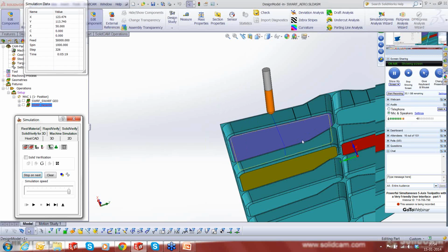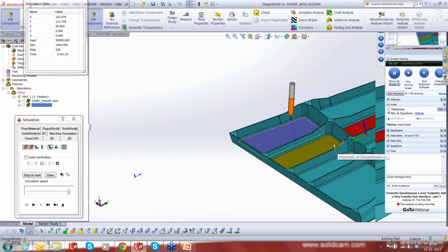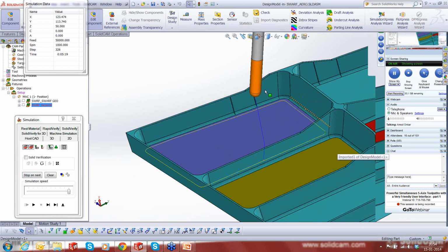Okay. This looks a much better result than what we got in the very first instance. Now, if the result has to be even better, then I need to put a few more tilt lines out here to control the way the tool is going to behave in this whole area. So the tilt lines are now changing the way the tool is going to stick itself to the surface. It's controlling both the tilt and the lag angles and making it much more effective than the automatic result, which was not so good.